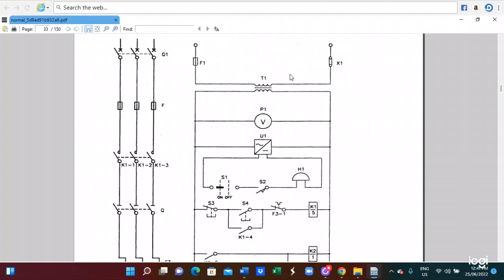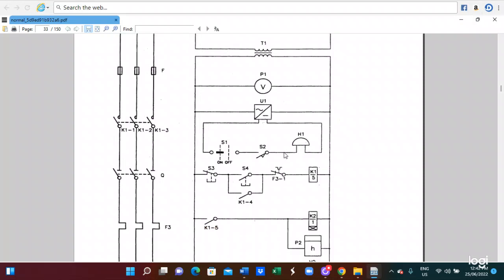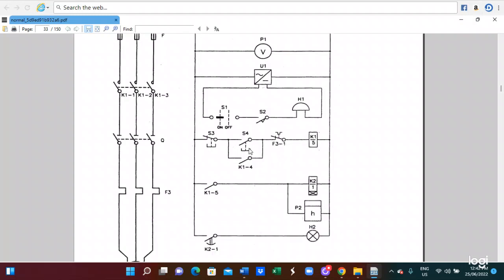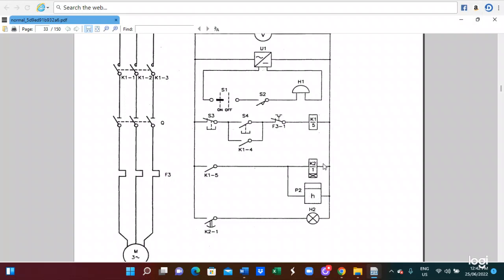This is power supply. This is transformer connected to the AC to DC converter, and those circuits are operated by the DC circuit. So this you can see the switch, and also this K1, K2, K3 conductor is K1's control coil. In the meantime, K1, 4, those are the auxiliary contact, and also this is for the signal contact for the H coil. This is the timer switch, and also this light. So this is lighting. So those are this circuit going to the motor control circuit.